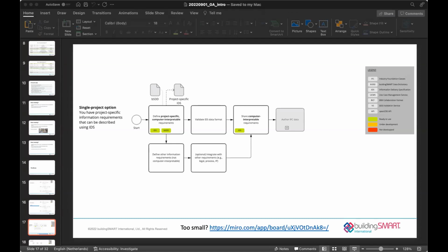So there can also be another use case where you have an IFC file and you want to further enrich it, or you want to further add some properties to it. For example, you are the solar supplier and you're getting an IFC file with solar panels in there, but those are just proxies or whatever. And you want to enrich that by classifying it according to the ETIM classification. So it's very similar to authoring, but you're just extending an existing file. So you're not really using an authoring tool.